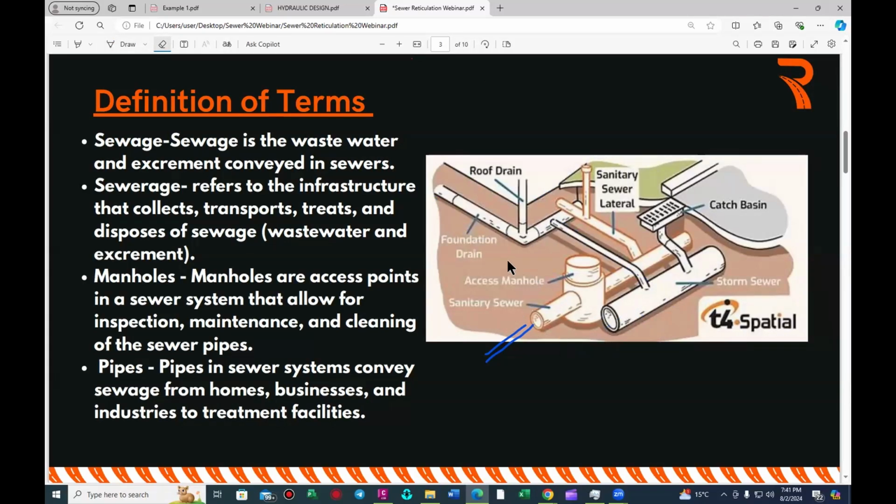that in our recent, what can I say, urban councils, most of the urban councils separate these two. There's a separation between your sanitary system and your storm sewer system, right? It's called a separate system. There are some combined systems that were used back in the day, but they are now updated.